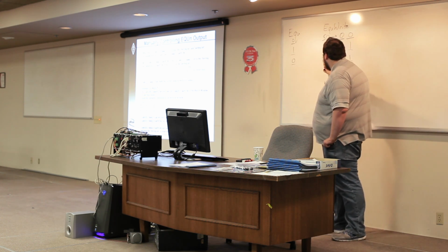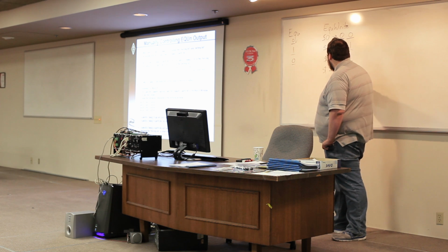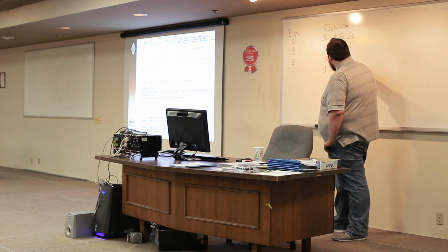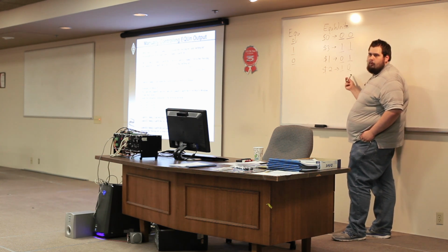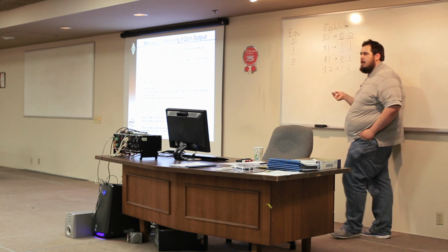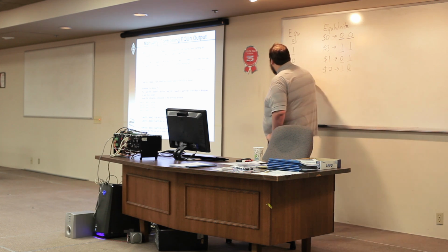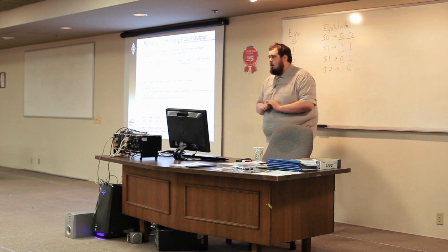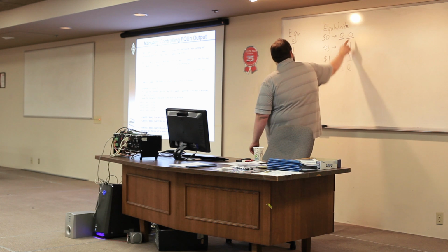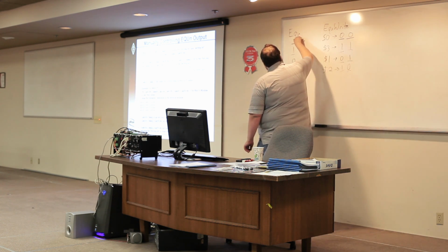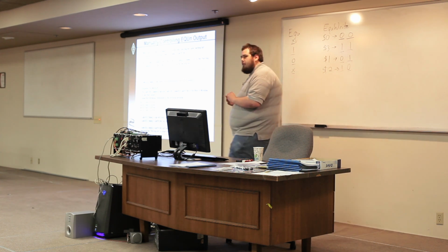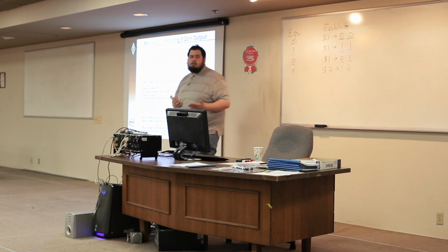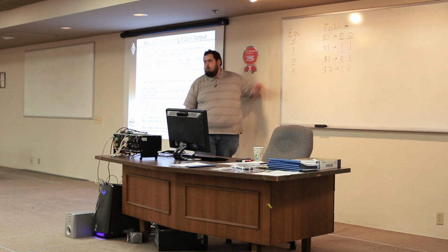And then the last case, if we have a value of 2, we have 1, 0. In this case, we are trying to write a value of 1, but our forcing bit is 0, so we're not actually going to write it. So we're going to retain the same value, in this case, 0. It might be better if I replace these two with x's, because what will actually happen in these two cases here is whatever the previous value of EQU was, it will not change, it will remain at what it had been.